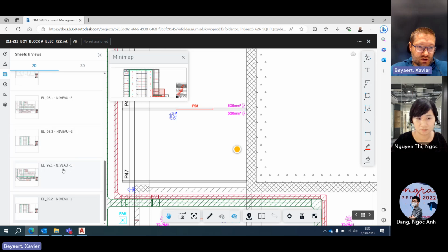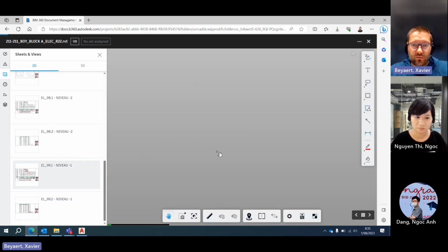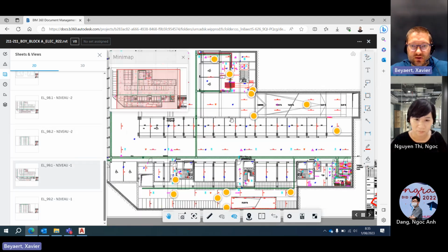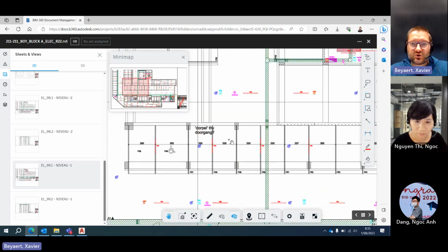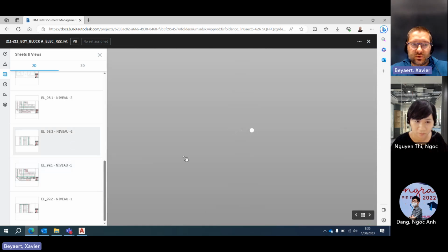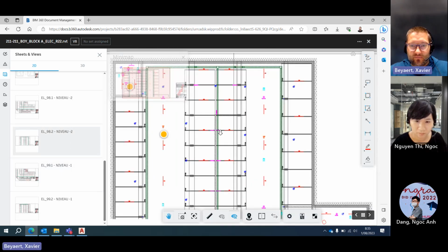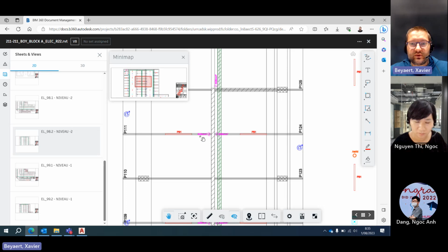The charging stations that are over here in the residential area also have 22 kilowatts, but they need to be divided for two cars. So if one car is parked, it can give 22 kilowatts to that car. If there are two, they both get 11 kilowatts. So that's the idea behind it.